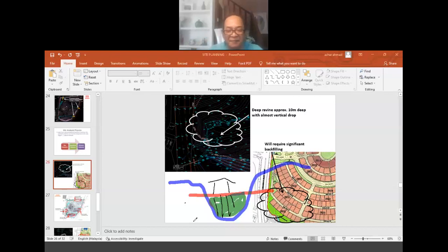We can advise the structural designers later on that, Mr. Engineer, you need to look at this foundation more closely because it is on a relatively thick fill area. So pile foundation would naturally work. The normal pad foundation would result in settlement, and this would cause problems later on.